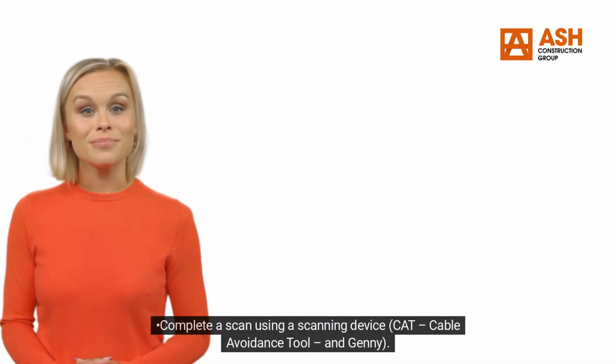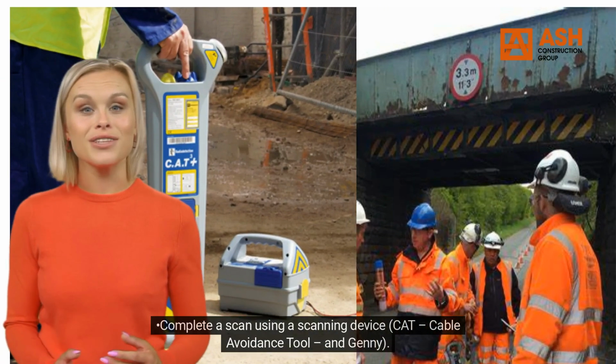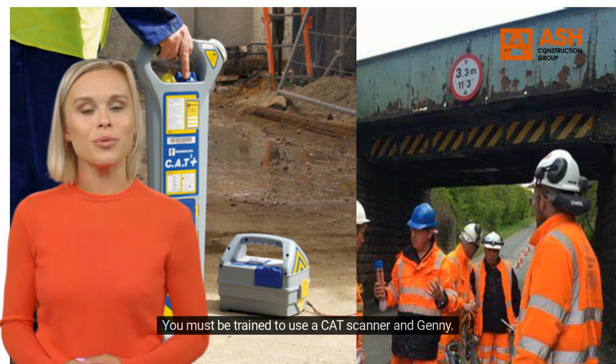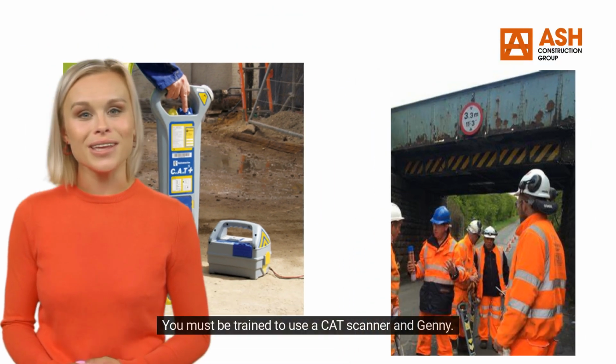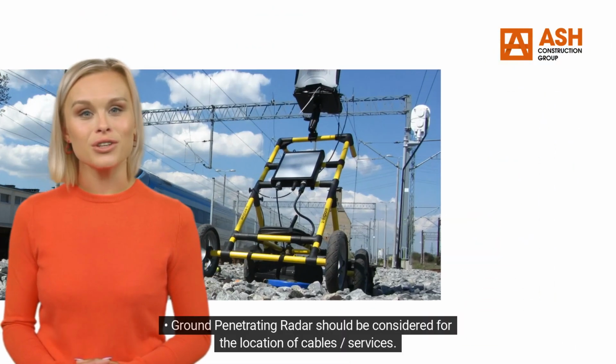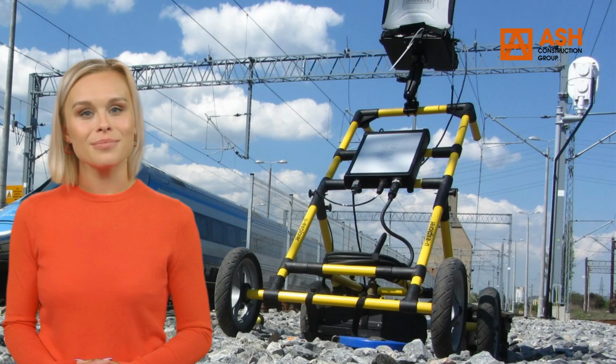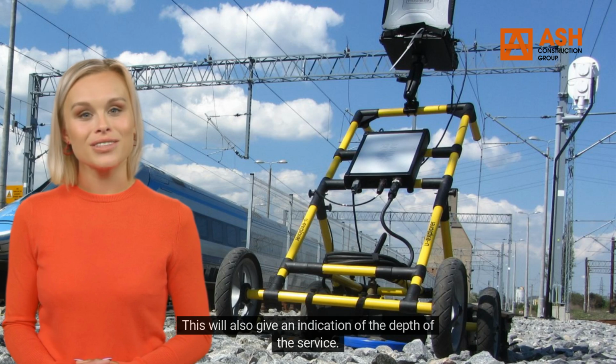Complete a scan using a scanning device, CAT, cable avoidance tool, and Genny. You must be trained to use a CAT scanner and Genny. Ground-penetrating radar should be considered for the location of cables and services. This will also give an indication of the depth of the service.